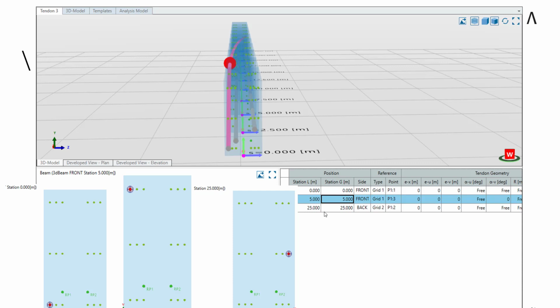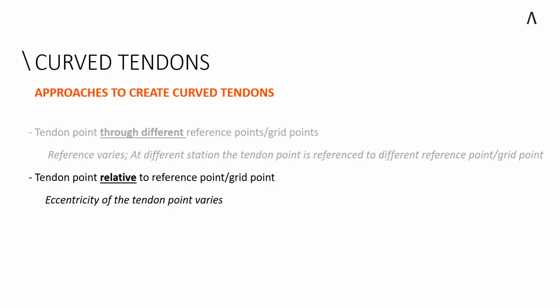There are just 3 points now, and between these 3 points a curved alignment is fitted. For sure, it's also possible to define certain points on many more stations. If you need it, you can put this constraint and it will accordingly create the alignment for you.